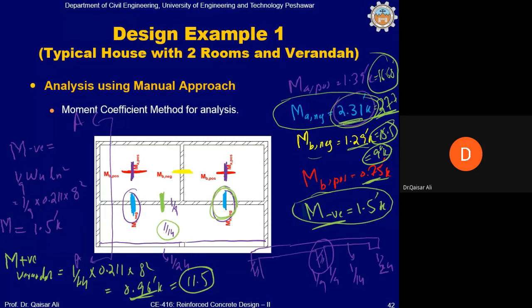तो आप क्या करेंगे? It means that you can provide the number 3 at 10 inch spacing everywhere except the top reinforcement at this support. उसके लिए आप ट्रायल एंड एरर से स्पेसिंग कैलकुलेट करेंगे. बात समझ में आ रही है?